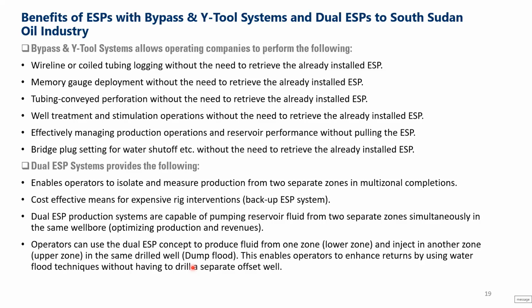And then operators can use the dual ESP concept to produce from one zone, the lower zone, and inject it in another zone, which is in the upper zone, in the same drilled well, which is the dump flood project, without the need of drilling another well.